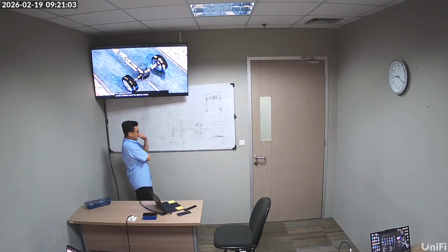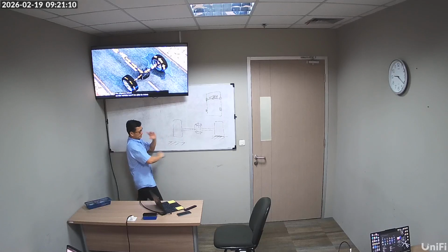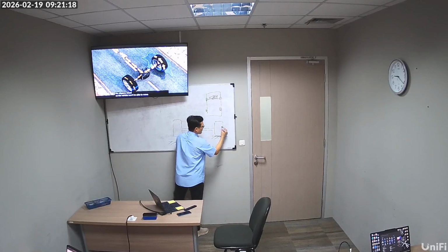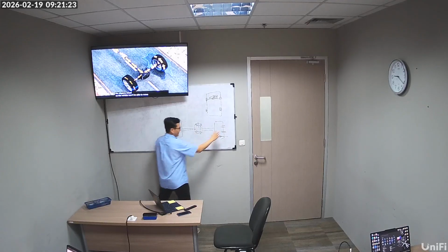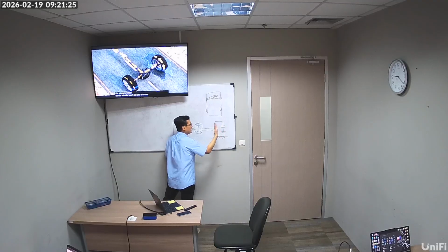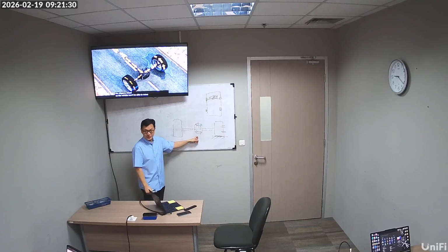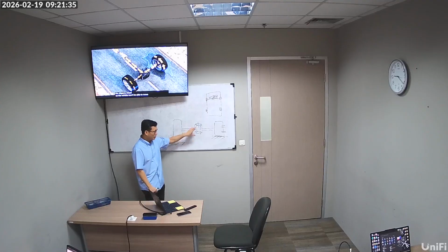Now, in this situation, if you're rotating the spider gear this way, what will happen? Let's say I literally bolted this to a wall. This is an extreme situation. This is bolted to a wall, so it cannot move. Can your engine or transmission still drive the entire thing? Will your transmission lock? No, right?